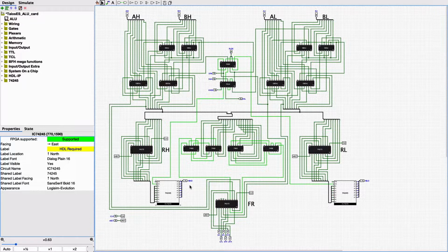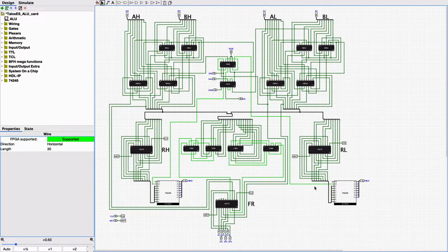It will either assert the internal bus on the high byte. This is internal bus high output, and this is internal bus low output. So that's the low byte of the internal bus, and this is the high byte of the internal bus. And if the output enable here is active, then this driver will assert a value on the bus. Otherwise, it will tri-state this output here, and somebody else will assert the value on the bus. That's how it works. Now, these output enable control signals here come from this control logic on top, this way, this way, this way, from here.